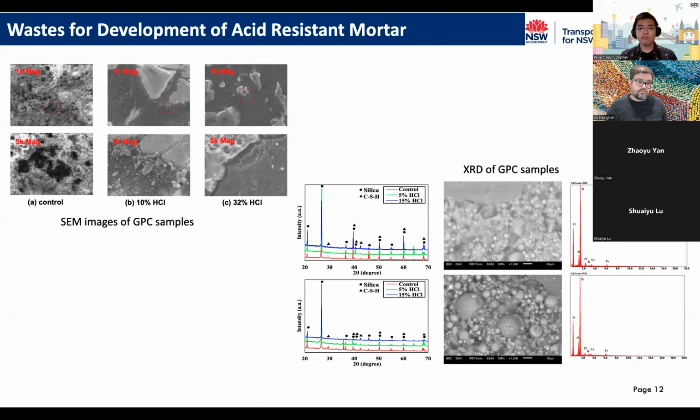When we compared that with control samples, we realized control samples had a much more homogeneous and flatter surface. Basically, these microcracks tended to initiate from the interface of aggregates, and then penetrated into that segregated, debonded area, and made complete debonding and caused the total failure.